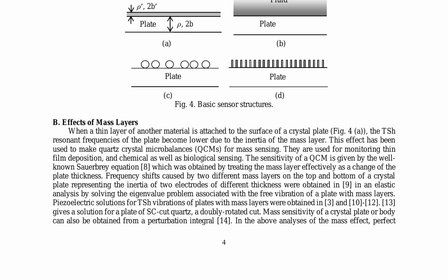The sensitivity of a QCM is given by the Sauerbrey equation, which treats the mass layer as a change of the plate thickness. Piezoelectric solutions for thickness shear vibrations of plates with mass layers have been obtained, and mass sensitivity can also be obtained from a perturbation integral.